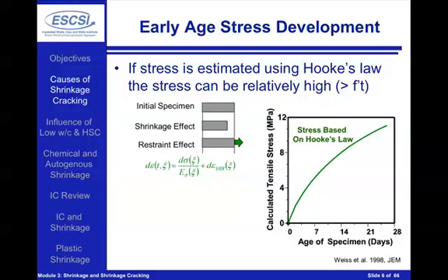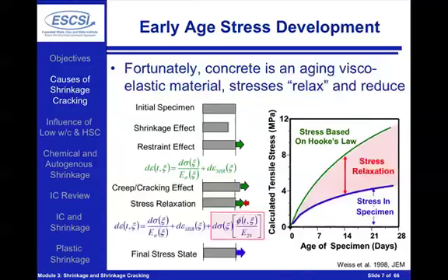And if we do a calculation like this, we can see that the tensile stresses will develop substantially over time, and when these exceed the tensile strength of the concrete, we can think about a crack that would be forming. So once we start to exceed 5 or 6 MPa, once we start getting over 400, 500 psi, we could expect cracking to start to occur.